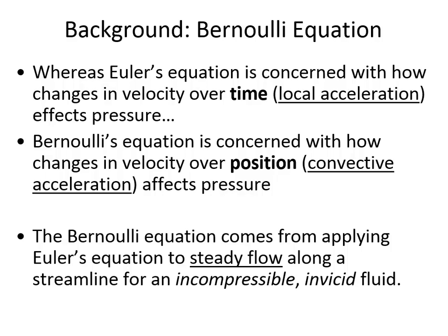According to Bernoulli's equation, it's really only valid if the fluid is completely incompressible. And neither liquids nor gases are. And even though gases aren't incompressible, we still apply Bernoulli's equation. We're still going to use it even when it doesn't apply, because the reality is Bernoulli's equation never applies.